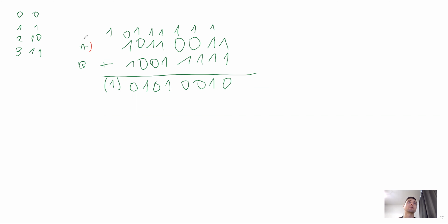Initially you would think, oh, we're adding two numbers, A and B. But if you look at it, in the first position, yes, but in all other positions, most of the times, we're actually adding three numbers. I made these numbers such that even in the second position, we're already adding three numbers. Here we think we are adding two numbers, but let's say that initially we set this carry to 0. So in this case, we're still adding three numbers. This one is A, this one is B, and the third number is C, carry. It's called carry because it is something that is carried to the next position. So actually we're adding three numbers.